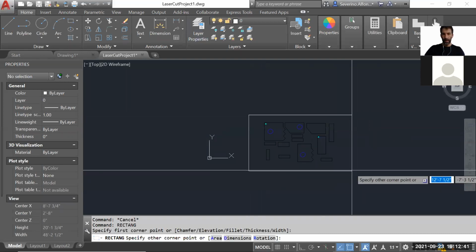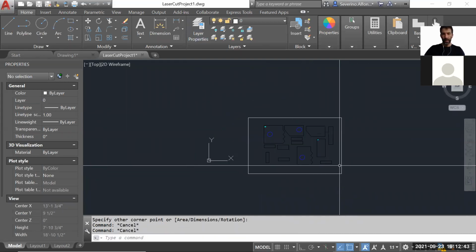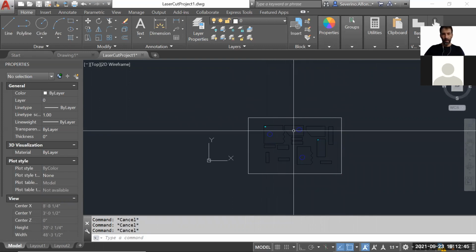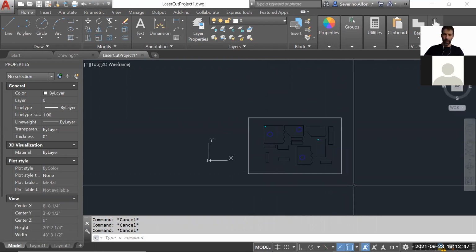So again, if you have a template in AutoCAD, let's say here, a rectangle, just something like that with an offset with the layers, it would be the same. Just organize them inside of the template, change the layers to the colors they're assigning to you, and then deliver this DWG file to your laser cutting manager to laser cut. It's essentially the same thing.